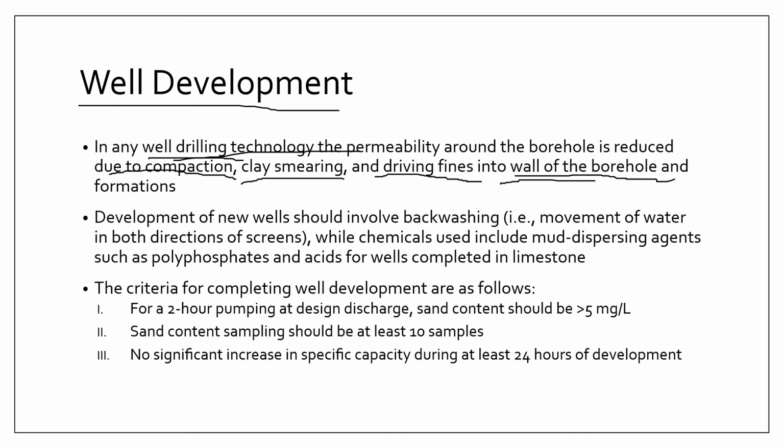These all serve to clog up or reduce the permeability of your aquifer. The objective of well development is to remove all those fines and mud that might be affecting your well or your aquifer.